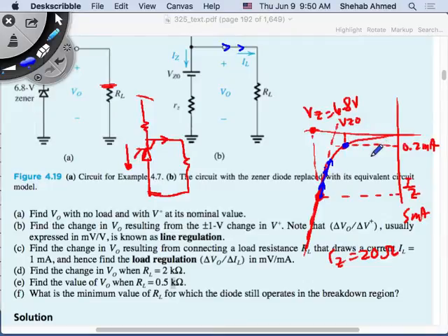Zener means what? It's not somebody's last name. Seriously, what am I doing with the Zener diode again? I'm regulating the voltage, right? If I'm operating around the operating point, that means I'm regulating the voltage. The application is a voltage regulation application, right? But if I move from here all the way to here, am I staying around 6.8 volts? I'm not staying around 6.8.